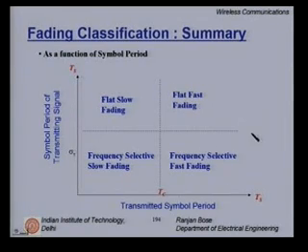The only link, as mentioned before, is Ts. Now, if on this axis we have Ts as also on this axis, somewhere we draw these lines. These lines on this axis is Tc, the coherence time, and on this axis the RMS delay spread sigma tau. So, this line is the RMS delay spread.